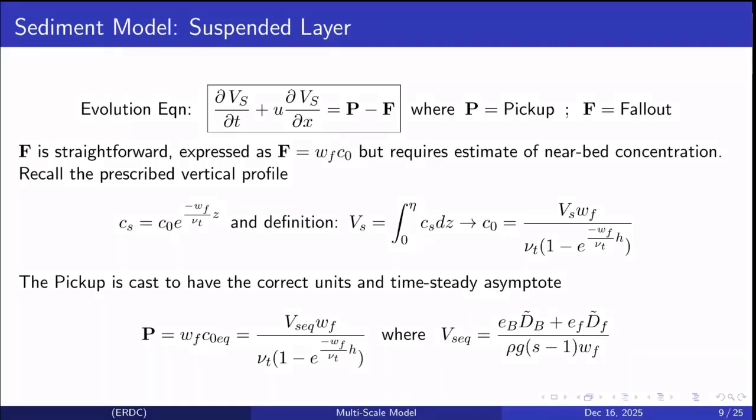The pickup is not quite as obvious. But it's cast to have the correct units and the time steady asymptote. So this one is more or less intuitive as an expression. But the pickup now is a function, much like the fallout, of the fall velocity and some of the details of the profile themselves, including the eddy viscosity or sediment diffusivity.